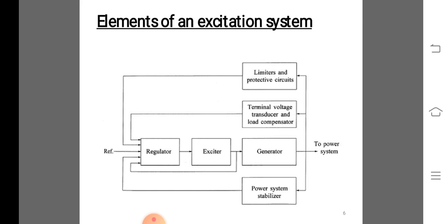Static excitation system. The generator field is fed from a thyristor network, just sufficient to adjust the thyristor firing angle to vary the excitation level. A major advantage of such a system is that, when required, the field voltage can be varied through a full range of positive to negative values very rapidly, with the ultimate benefit of generator voltage regulation during transient disturbances.